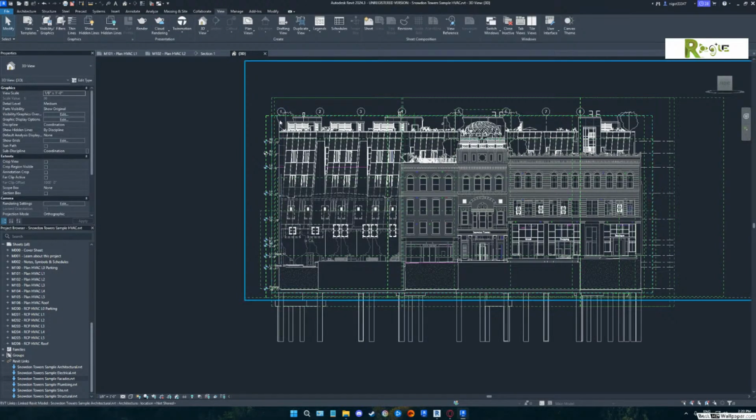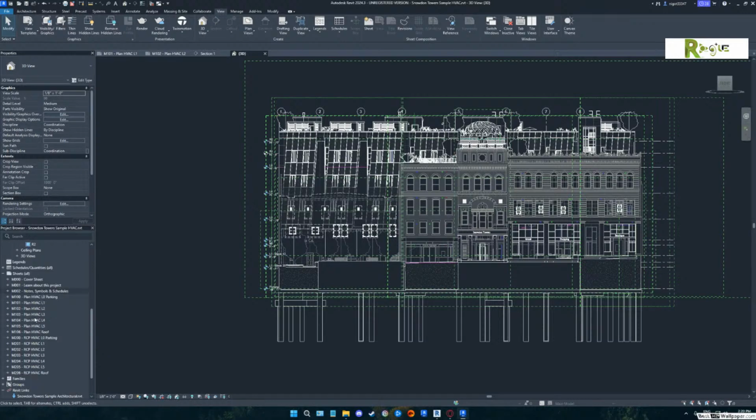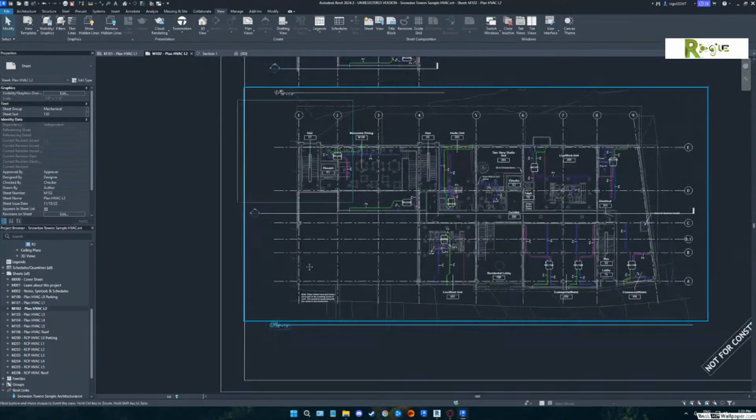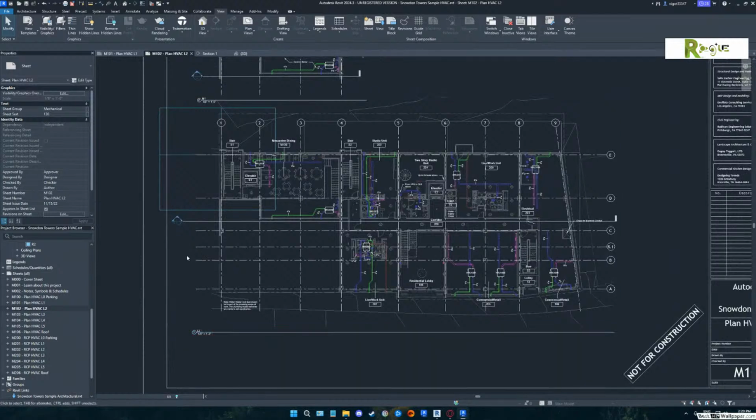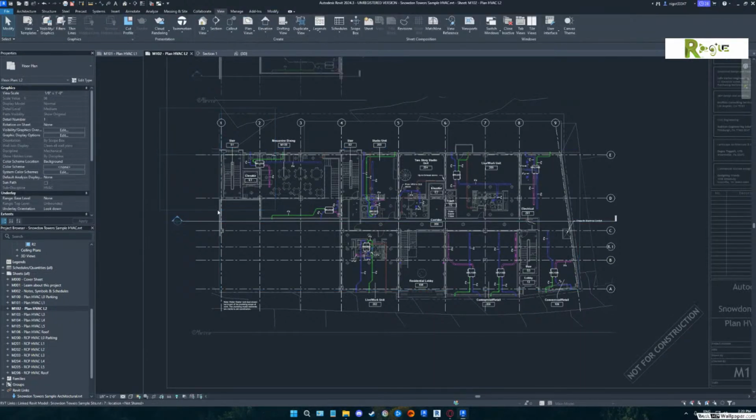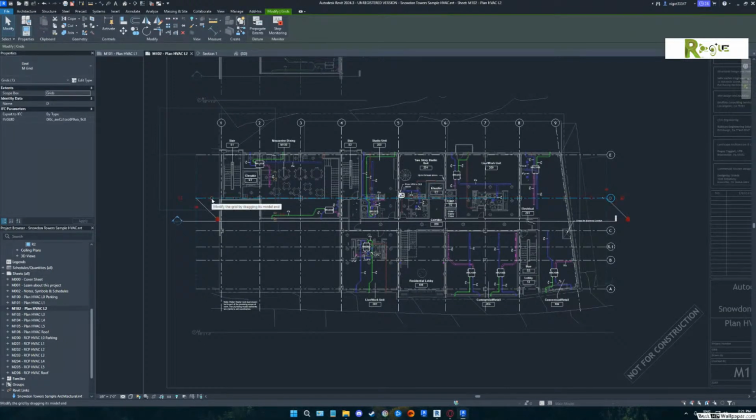Do me a favor, go to one of the plan views. Yep, that'd be fine. You can get that same problem with the column grid as well, but you're not having it in this one because they're all attached to scope boxes. So if you double clicked in that plan view and you went to one of your level lines to try to stretch the column grid, see how you can't stretch the column grid at the side? No, it's locked because it's locked to a scope box.